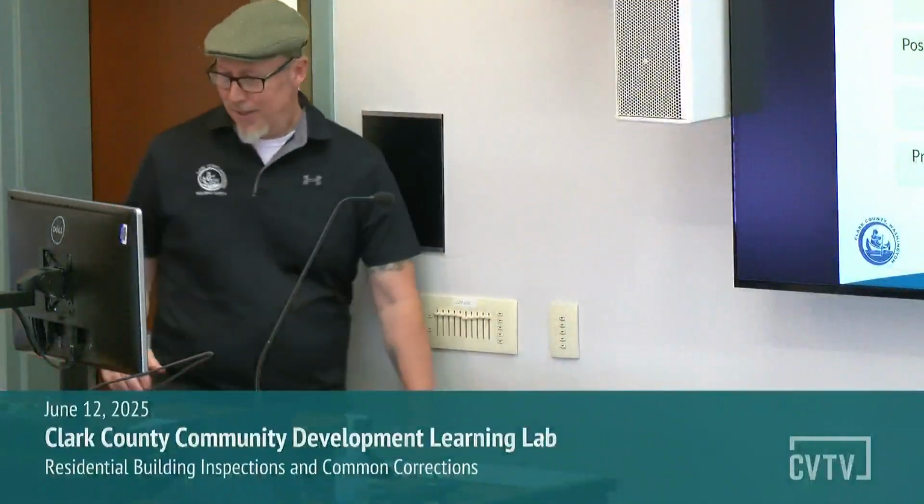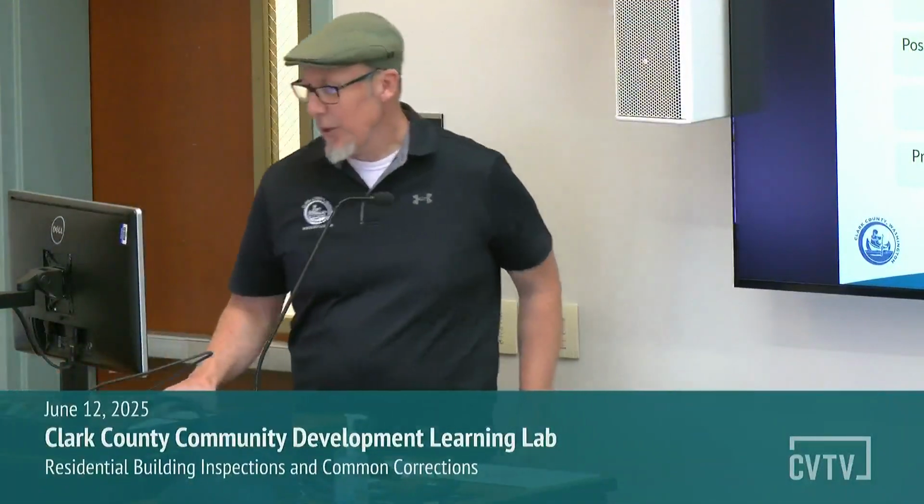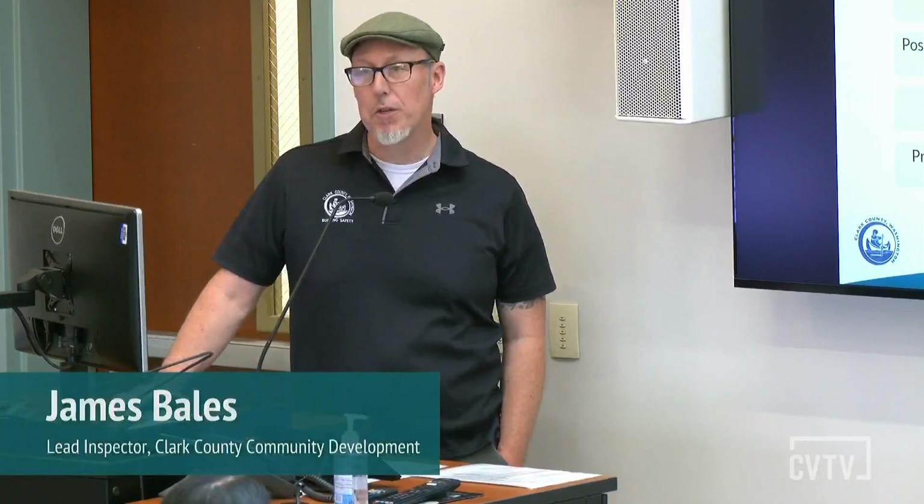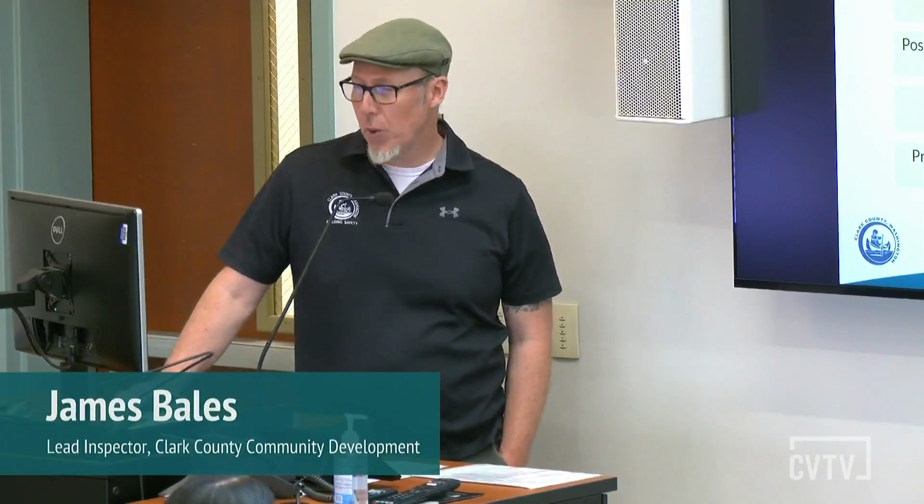All right, thank you, Eric. So I'm going to talk about post and beam, and for those of you that don't know, a post and beam is essentially what's going to support your floor in between the foundation walls. We're going to want to verify point loads and floor joist layout. Any plumbing pre-deck has been installed, and this is all the plumbing that will be below the floor.